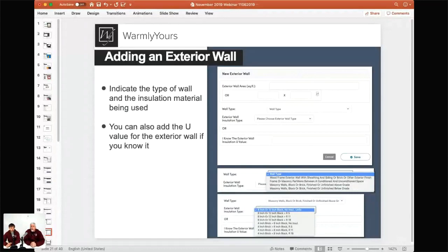Once again, kind of recapping as we go along. If you have a room that has 0 exterior walls and you have a room that has 3 exterior walls, which one is going to start out colder? Definitely the one with more exterior walls. Right. So that is, once again, getting the common sense into the calculations here. You can start walking into a space and go, oh, this might be a good candidate because there's no windows. All these walls are interior walls. There's no exterior. Okay, so let's do a calculation on that.